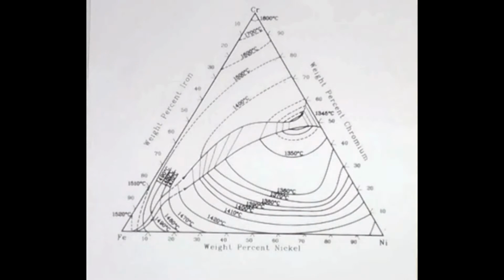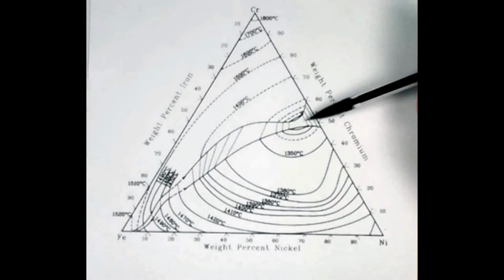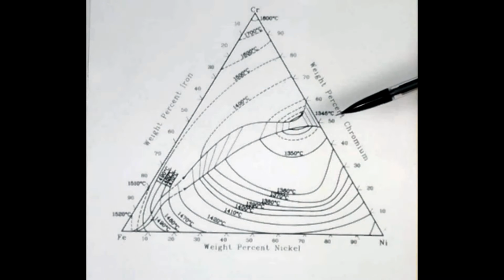These temperatures are the points where crystallization occurs. The center line below is the boundary trough for the eutectic phase. To determine the composition, there are two methods that can be used. The first method consists of drawing parallel lines to the side opposite of the triangle.